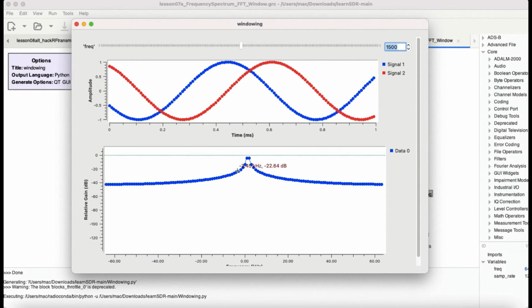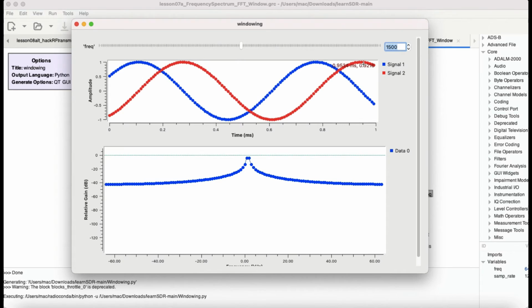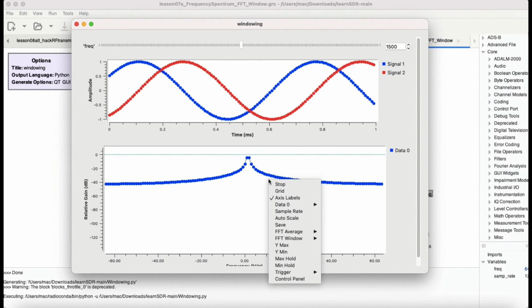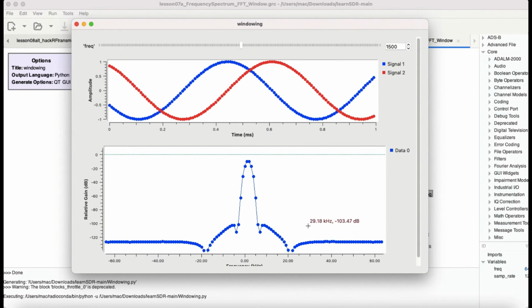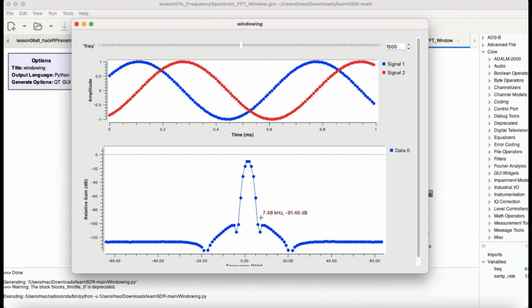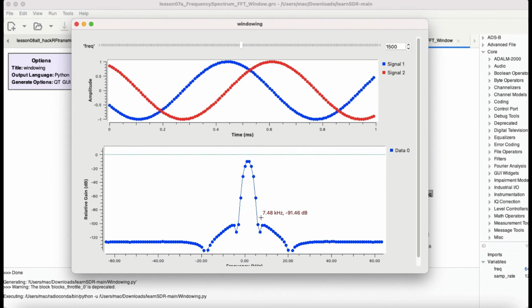As you can see, your side lobes are quite high. It's not properly smoothed out. Now when I change this to Blackman-Harris, look at this, how nice that function looks. So how are you going to choose your window? Choosing a window is actually not an easy task. You've got to remember a few things.